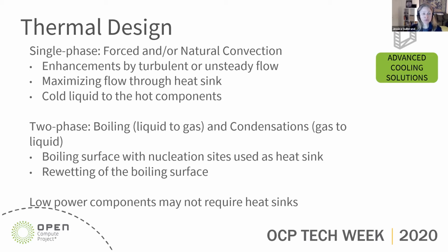And the trick here for two-phase is being able to re-wet the boiling surface. So as the bubble takes off, you want to make sure that the liquid has a quick entry into the boiling surface again, to make sure that you have continuous heat transfer from the hot components. And in immersion, which is different from air cooling, the low power components may not require heat sinks here. So those could be removed.